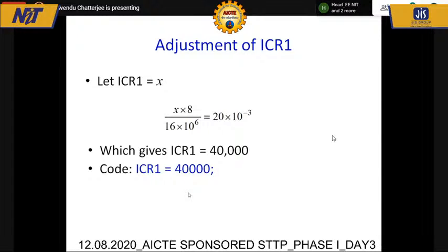This is the advantage of Arduino, that everybody uses it right from the beginner. If you cannot compute the hex value, if you have jumbled up the hex value and binary value, you can directly put binary and put the register values. If you have X values in the datasheet, you can put that directly. Now I have a decimal value, I can also put that directly without any problem. So I have given ICR1 equal to 40,000.